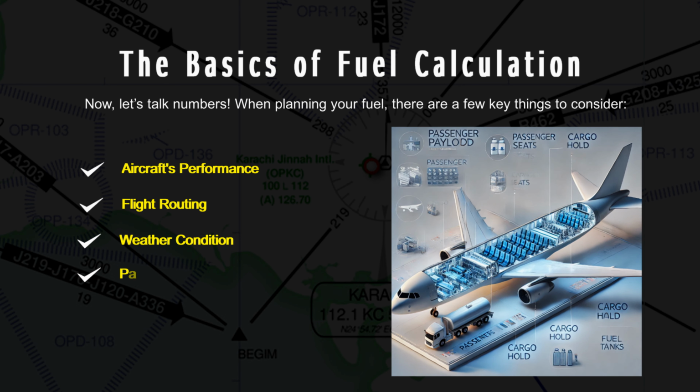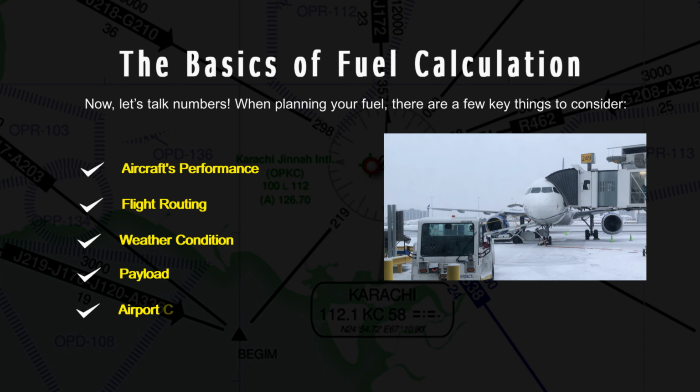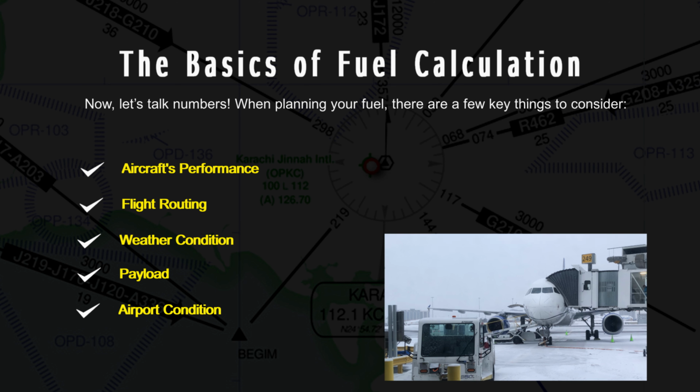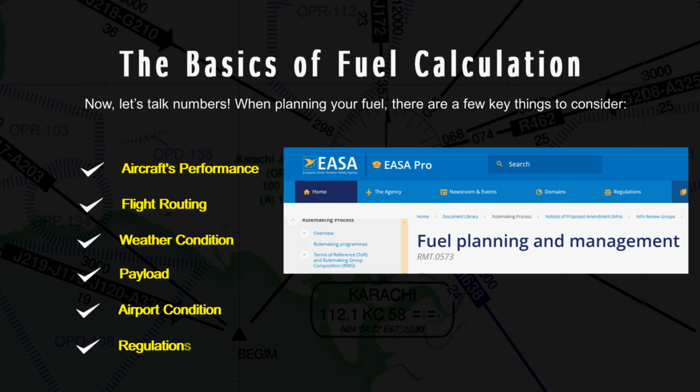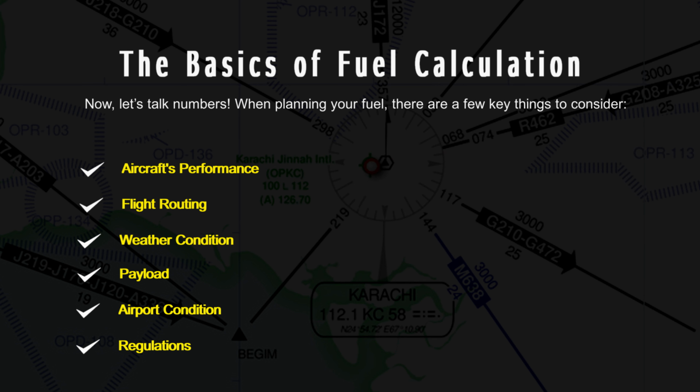4. Payload, weight of passengers, cargo, and baggage. Heavier loads increase fuel consumption. 5. Airport conditions, runway length, elevation, and expected delays, e.g. busy airspace. 6. Regulations. National and international aviation authorities, e.g. FAA, define minimum fuel requirements.